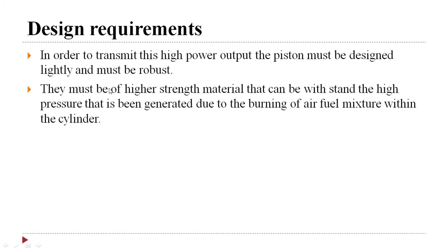They must be of higher strength material that can withstand the high pressure generated due to burning of the air-fuel mixture within the cylinder. Due to burning of fuel, high power is generated, and due to this there is high pressure and high temperature inside the cylinder, and we have to design the piston to withstand this high pressure and high temperature.